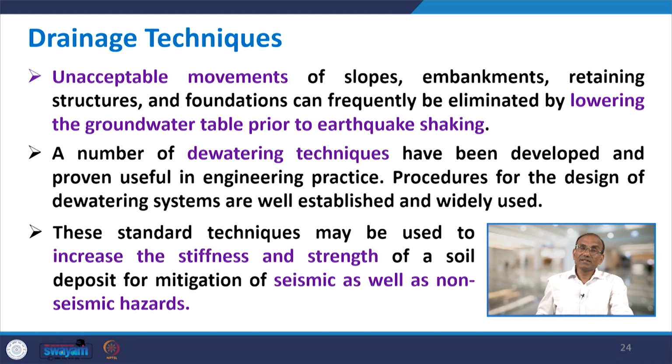Basically, in case of soil, many of the issues are related to pore pressure, and even for clay soils where liquefaction is not an issue, if you remove the water or pore water pressure, then automatically its strength will increase. So, if you want to increase the strength and stiffness of the soil, one thing is to pump out the water using some drainage techniques, and half of the problem is already solved. But of course, this drainage or pumping out the water may not always be possible.